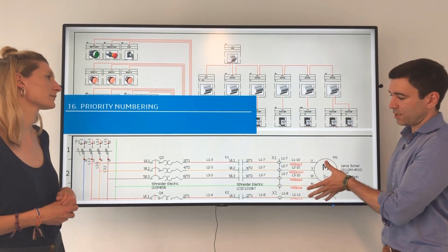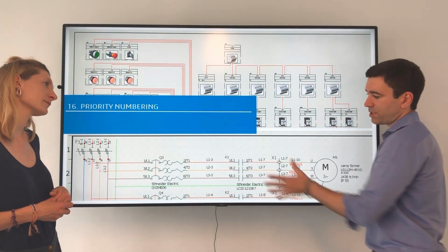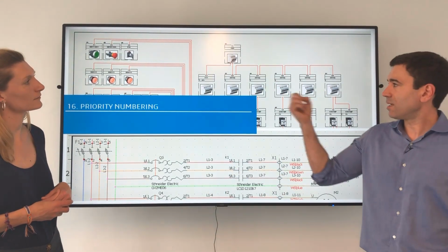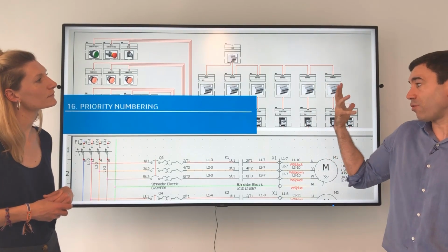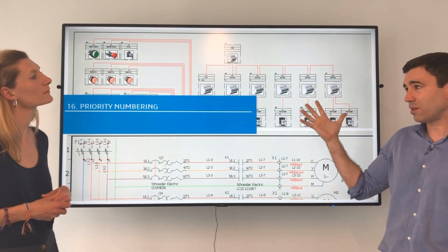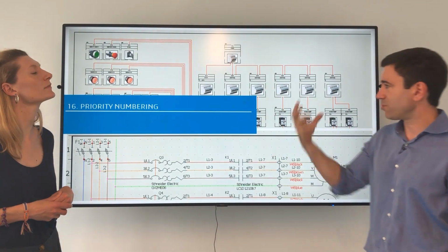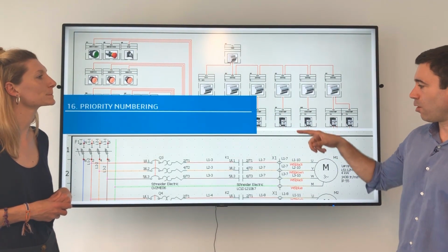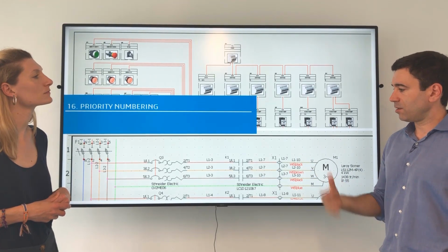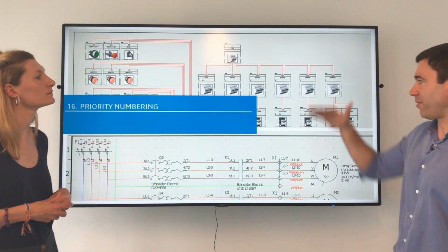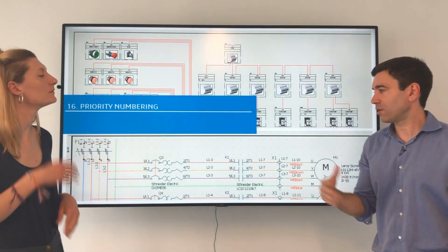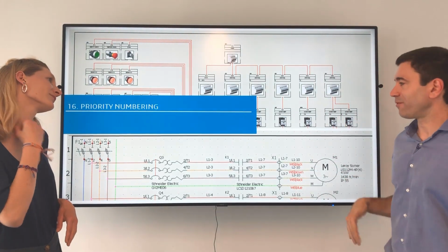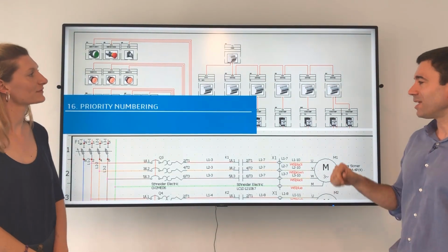One is the pure electrical drawing that you can see here, and the other is a visual drawing that we call synoptic or cabling diagram. It's more visual. When you number the components, you number them from top to bottom. It could be from left to right, but we do it from top to bottom.